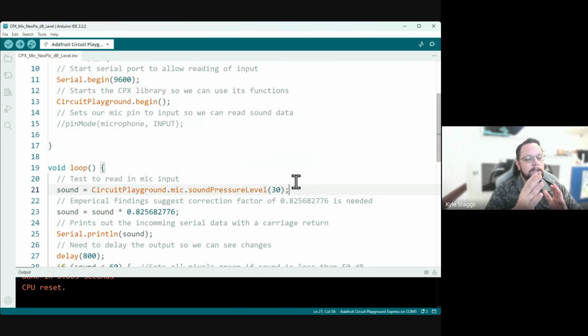But then we also have to teach you about storing data into arrays, not just as a single integer. And then you have to look at, based on even what we're seeing here, even if I'm slowing it down, the rate it's reading data is so fast, the rate it's changing is so fast compared to what the output level is. We need to start learning how to do moving average windows for data for sensor development. And that starts to get into actual signal processing things that are usually reserved for a signal processing class. So we're trying to teach you guys many levels and layers of things all at the same time.